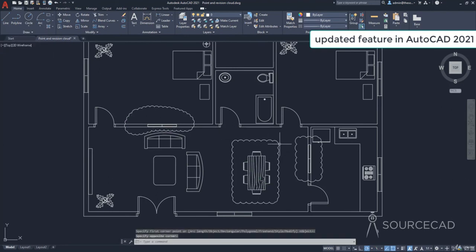So in this case, all the arcs are of equal lengths, and you can just visually compare it as well. So that's a subtle change. If you want to make this change, you can do that. And this rev cloud arc variance is a new system variable added in AutoCAD 2021 only. So if you are trying this system variable on older versions, you won't find it.